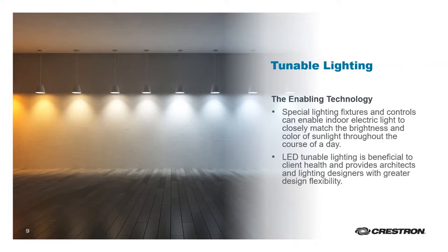Tunable white lighting becomes circadian lighting when we simulate the daily sunrise to sunset curve by gradually adjusting color temperature and intensity accordingly. These dynamic lighting parameters also allow us to provide physiological or wellness benefits. If our internal body clock cannot always take its cues from sunlight, we can do so with interior circadian lighting and thus counter the effects of our perpetual indoor lifestyle. Studies have shown this improves mood, sleep, and overall sense of well-being.